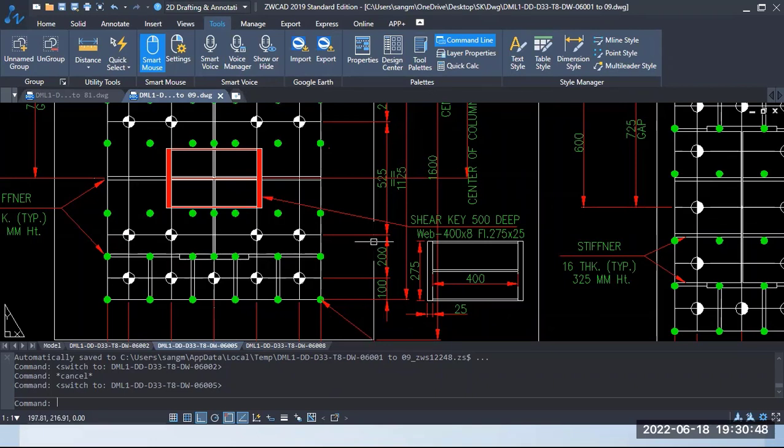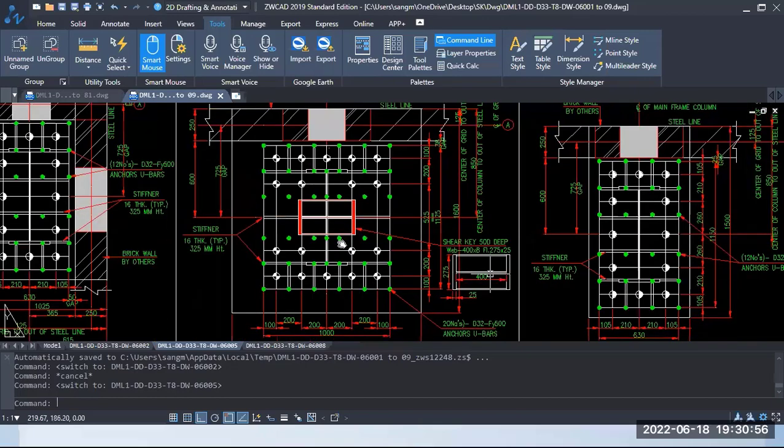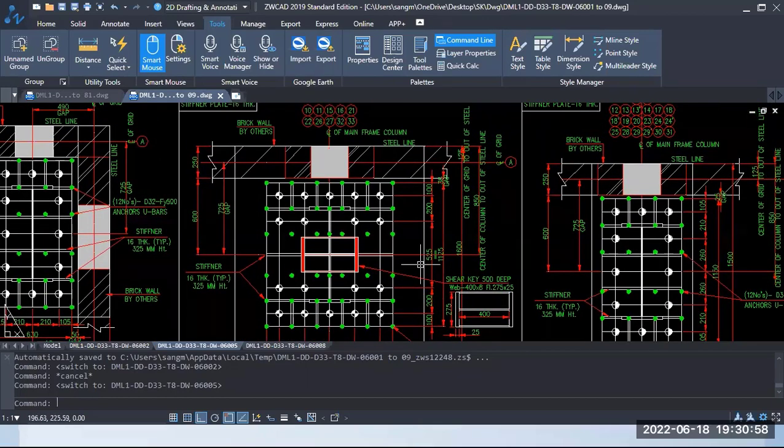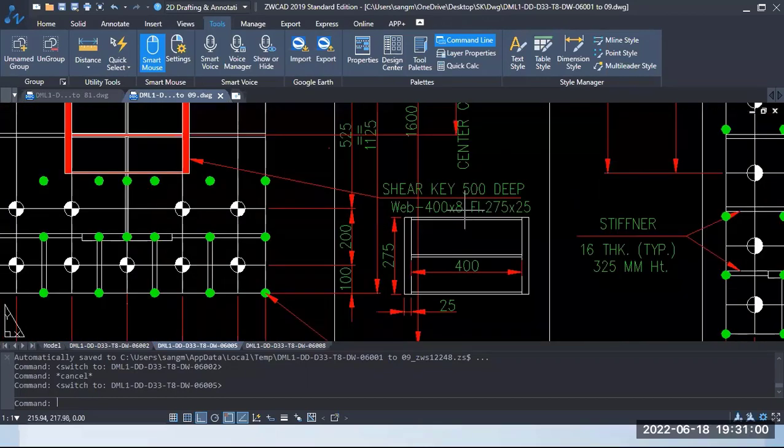It doesn't recommend transferring the shear force by the anchor. So in that case, we have to provide a shear key. So we have proposed a shear key here. It has a depth of almost 900 mm, and all the details we have mentioned here. The shear key has a 500 depth, and an I section we have proposed here.